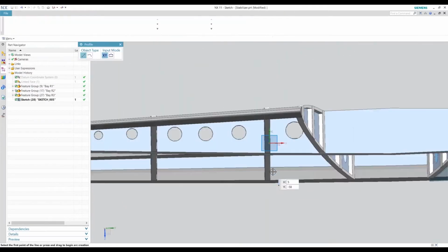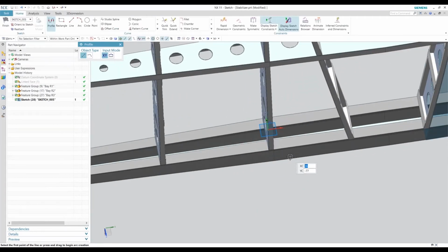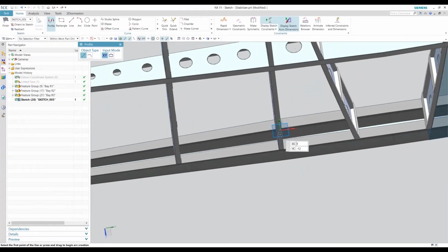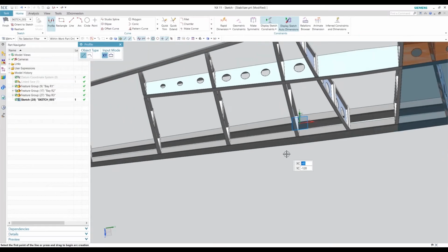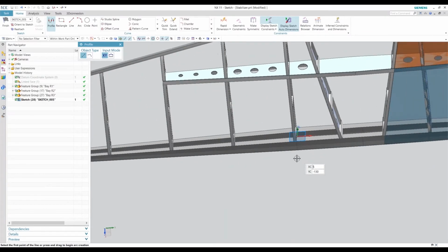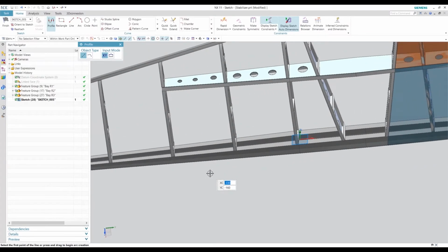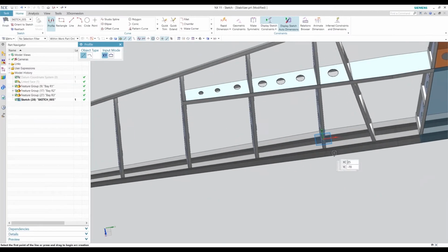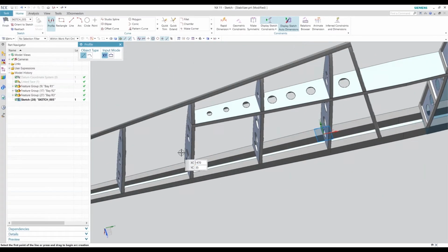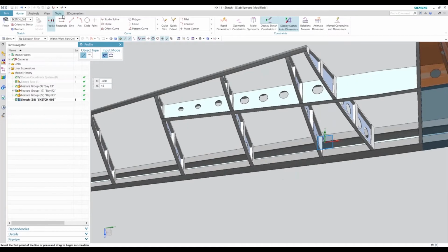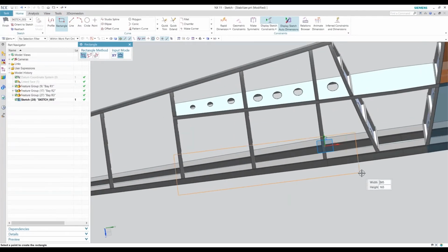Okay. We won't get into the specifics of the dimensions and your coordinate system placement, but just keep in mind that when you're working with a production model, you'll want to have a purpose for all the dimensions there. So let's first create a rectangular boss.